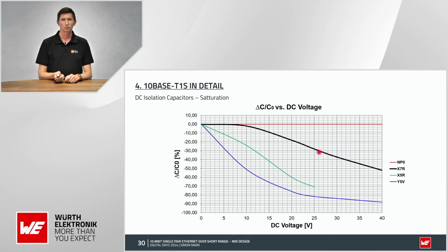And here we are on the line where we can look for the saturation. For example, for 15 volts, we have a loss of 10% of capacitance. At 20 volts, close to 20%. And so you can look for your capacitor and then find the point when it's saturated.